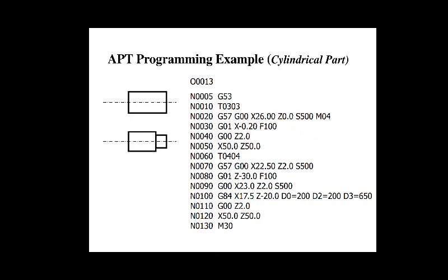After facing, if you observe in N004, we inserted G00, which means after performing the operation the tool should move rapidly to the position Z2.0.